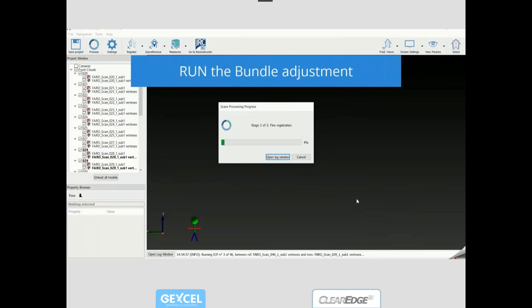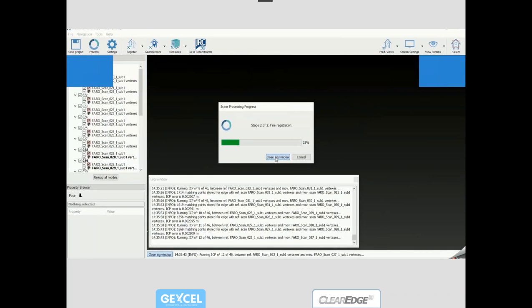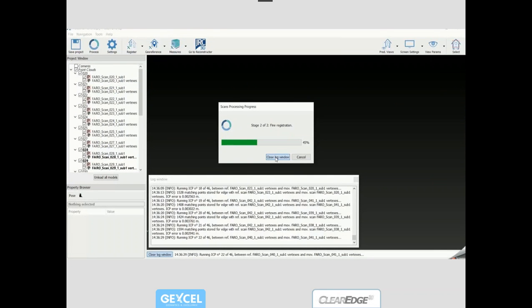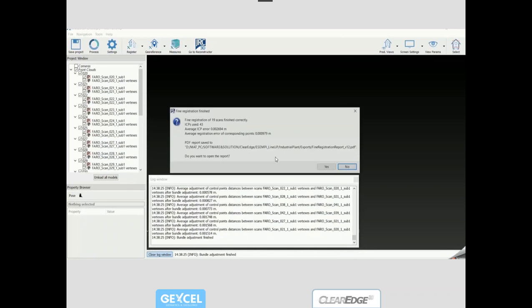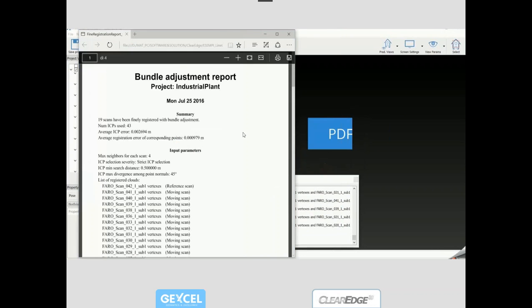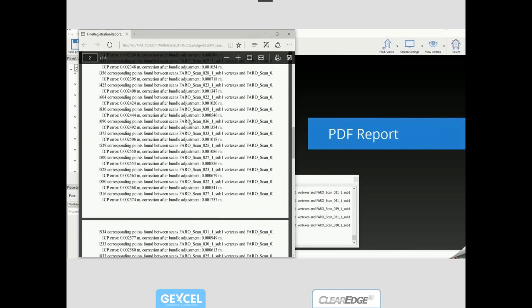Then a best automatic alignment run that is not, as Mike told you, just a cloud-to-cloud registration, but there's also a global optimization within the different scan edges. So the ICPs between the different point clouds are run, but then there's also a final global optimization that, especially if you have good loops, has improved your final result a lot. At the end of your process, as Mike also explained, you have very useful reports that also help you understand if something is wrong.